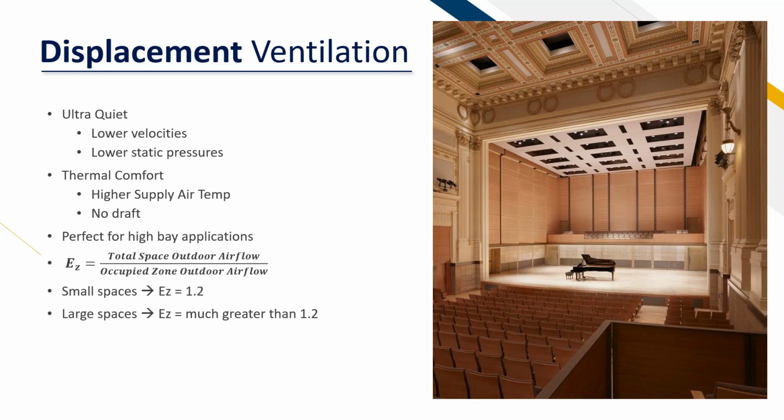They were engineered so that the air leaves those diffusers in a laminar pattern and hits the floor at optimal velocity, at that 20 feet per minute per se. Then it pools right at the floor and helps cover that extra area that wasn't covered by the sidewall diffusers. It sounds counterintuitive sometimes when you think about overhead displacement, but with these Price products, we're seeing more and more applications where we can use those with great effectiveness.